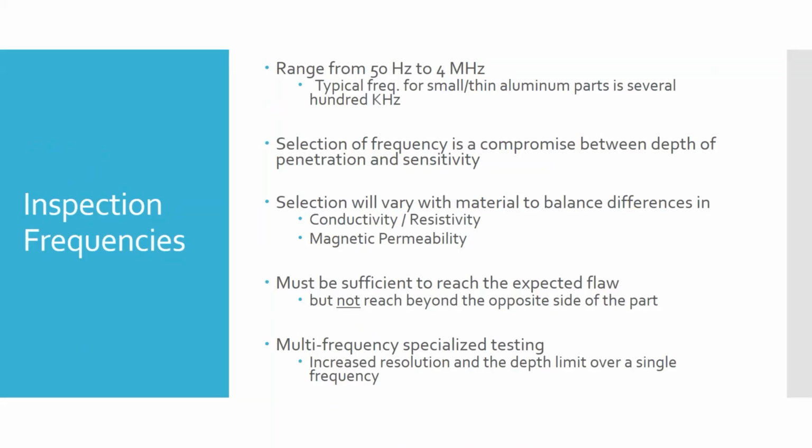We have to check the compressor or the turbine case on the engine, because that gets hot and cold and hot and cold, and things that get hot and cold expand and contract and tend to crack. Okay. So we get an idea of whether it's a surface crack we're looking for, or lap splice corrosion. Do we need deeper penetration into the base? You have to keep that in mind.